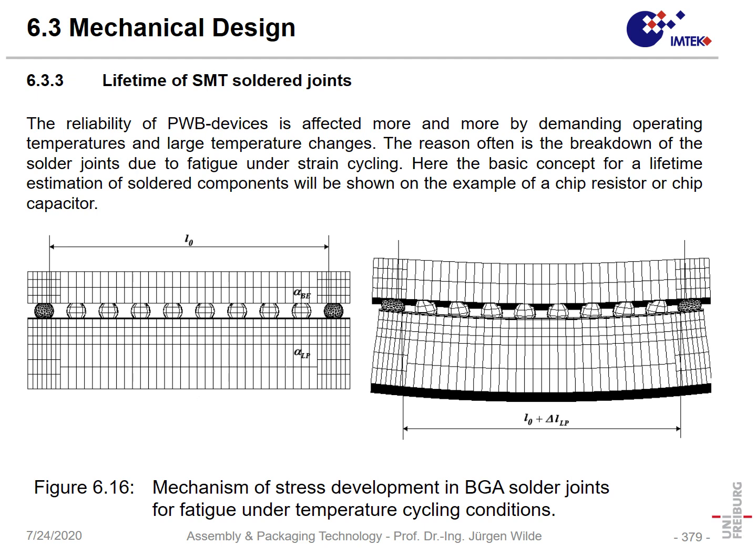We must also say that typically such computations are done by finite element method. Okay, in that way we have at least a method to estimate stress in systems, for instance, when we have mounted a chip on some substrate. But now let's look at another situation.